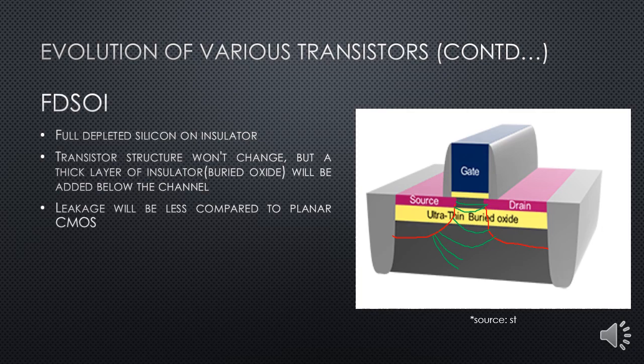So it has one kind of advantage. I can say it has better control over body bias and is dynamic. I would like to explain what it means. First of all, I want to explain what body biasing is. We have the substrate underneath here, this dark gray color is the substrate. We apply some potential to the substrate, and we call it a body bias. The substrate is nothing but the body, and some voltage will be applied to this. As we have the buried oxide layer, body bias plays a prominent role over here. So we'll have some potential applied over here, and it will be connected to my body bias, the body.